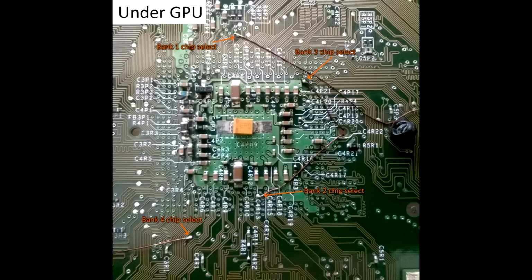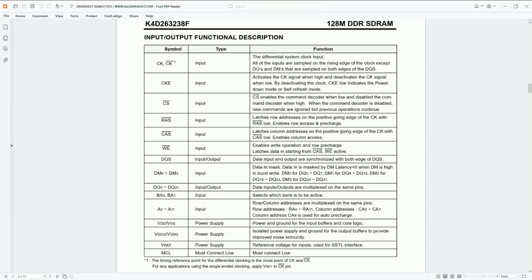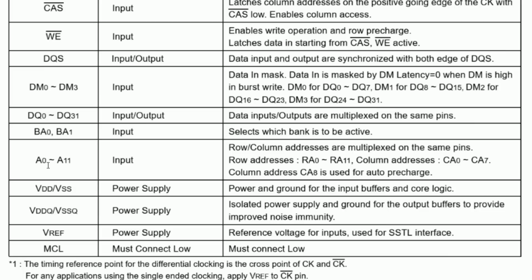So my first thought here was I need to understand how this addressing works. So what I did was I found the datasheet of that chip that the Xbox uses, and here's a list of the pins. So of interest are the address pins here, A0 to A11. If you just look at that without thinking about how the addressing works, then that is not enough bits. Right? If you have 8 chips and you have 12 bits, then this is nowhere near enough memory.